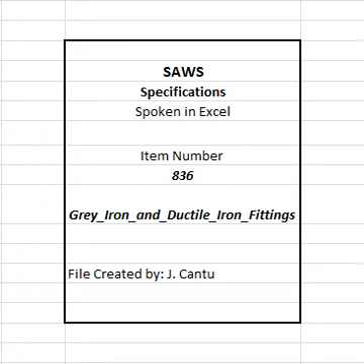4. Payment for fitting weights listed in Table 836-1 shall be full compensation for excavation, installation, anti-corrosion protection, select anti-corrosion embedment material and installation, hauling and disposition of surplus excavated materials, all glands, bolts, nuts, rubbers, and flange gaskets of whatever type required, and concrete thrust/reaction blocking, if required. 5.